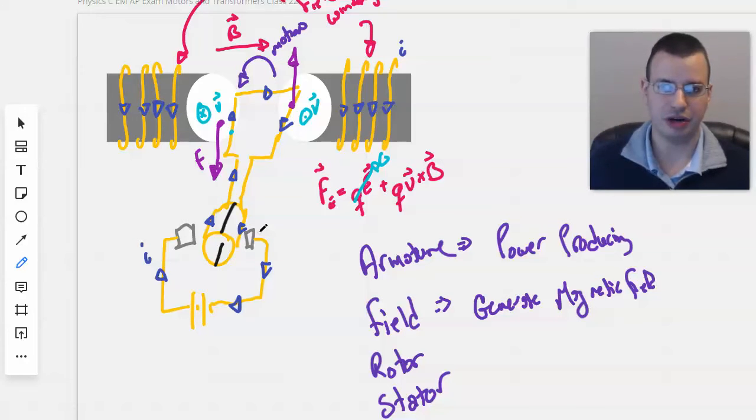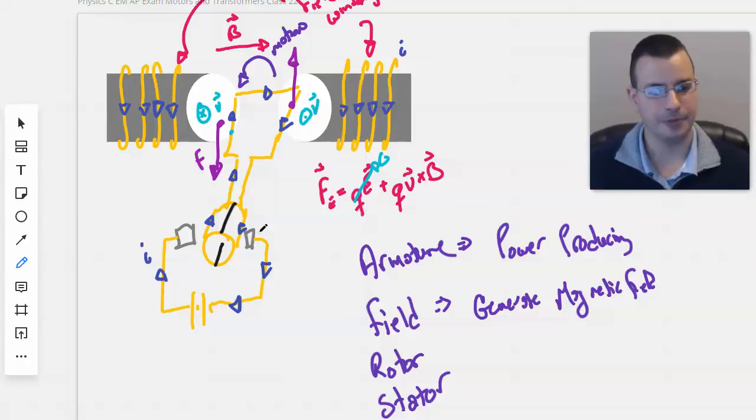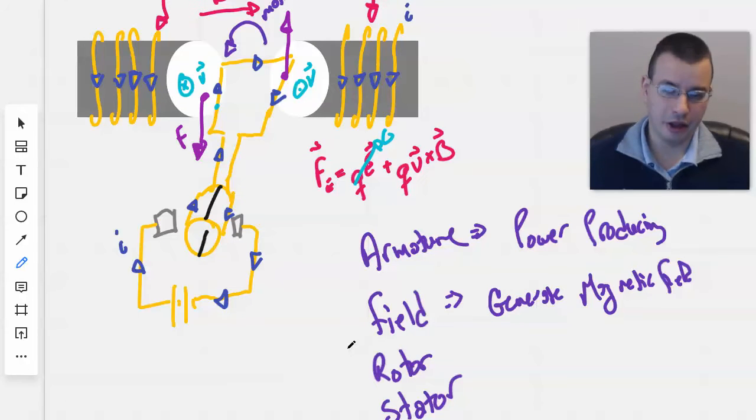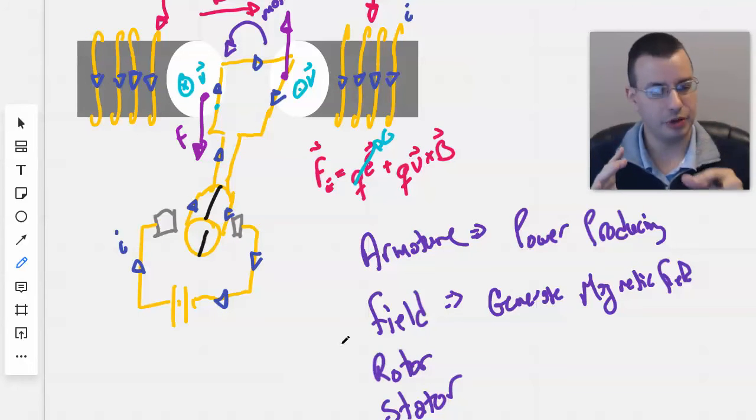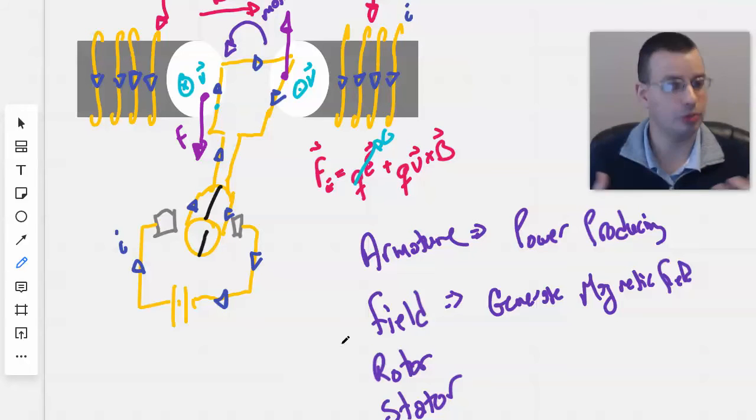So it's generally preferred through design to have the smaller amount of electricity going through your rotor. Generally you'll try to put the field windings and your rotor together, but not necessarily, because when you have relative motion and are trying to maintain electrical conductivity, it's more difficult.